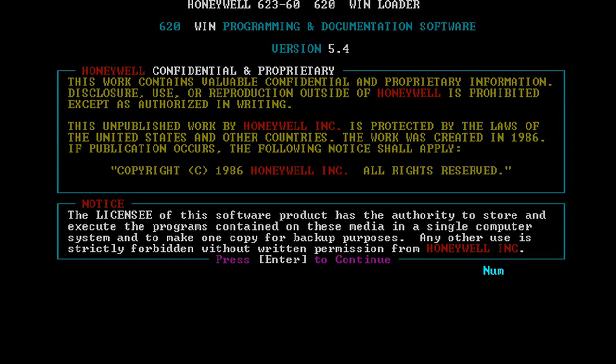This will most likely be a 62360-USB or 62360-cab. The cab cable connects to a conventional COM port on your PC, whereas the USB, as I assume, plugs into USB. Whichever cable you use, it's important that the COM port is configured for either COM1 or COM2. If you don't know how to do this, I have a datasheet that will help, and I will show you the URL where you can download it later in the video.